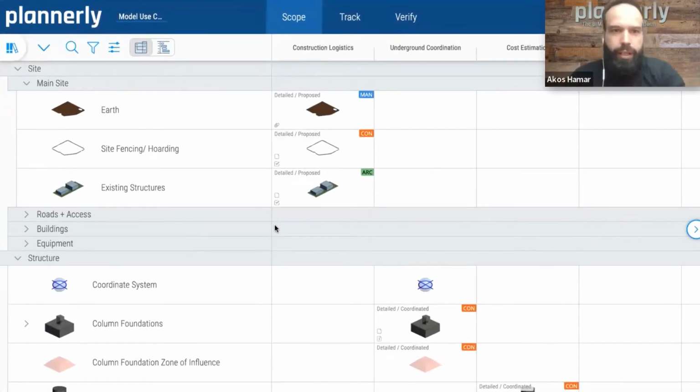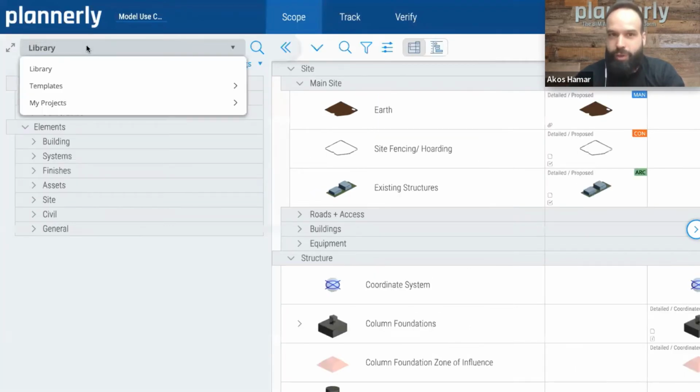If you think about it from an ISO 19650 perspective, for example, we are creating here the information containers, right? And these information containers would be pieces of information that we can manage through the entire project, from the very first draft till the handover and management of the project. So first defining the purposes why we are doing something, then in a breakdown, finding out whether it's just a list of elements, items, tasks and deliverables that we have to create, or putting it into a more sophisticated classification structure, whichever serves your needs the best.